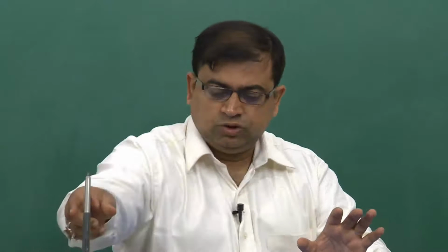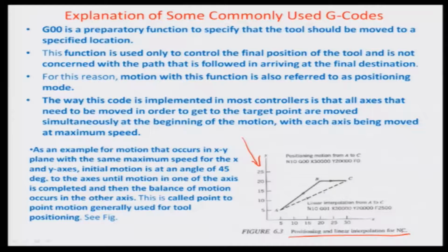Obviously, you want the tool to go as quickly as possible to the start of the machining process, and therefore you need to give it a rapid positioning aspect. So, having said that, with all this knowledge which I have discussed over the last about 5 minutes, think of it that if you had a situation where the x and y coordinates are not uniform in nature.